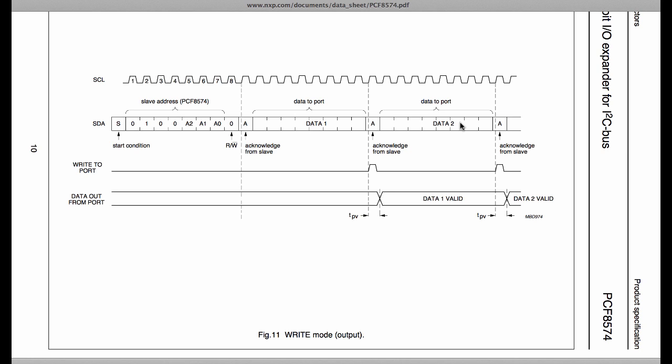So this would enable actually to use this port extender to transmit varying data over time. So you could use it as a parallel port, for example, and simply turn it on once and then send data bytes that would be subsequently put on the digital pins of that chip.